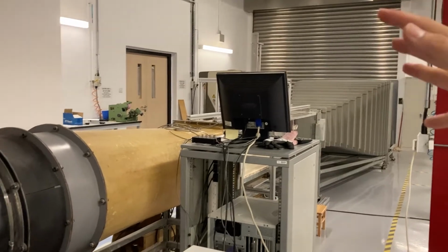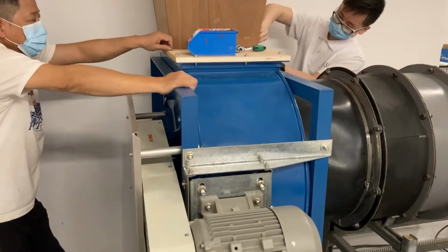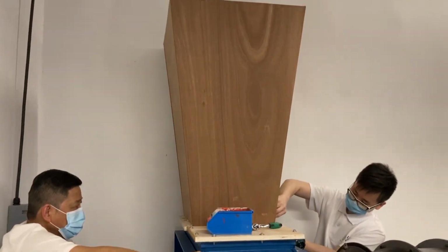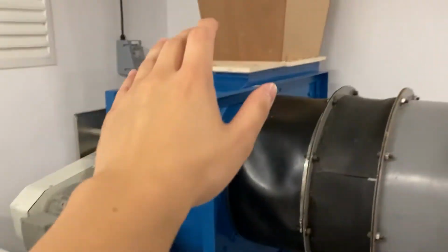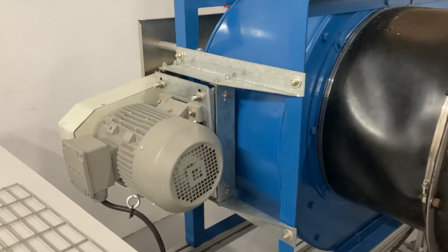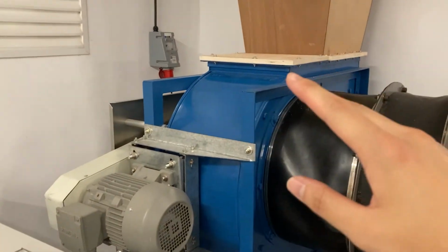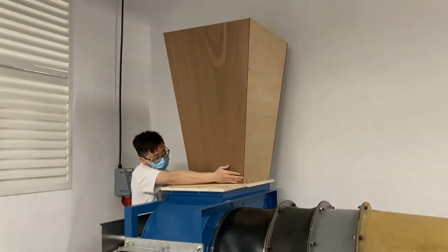So basically, you have the air being sucked in from up there, from this fan here, and out this diffuser that is being newly installed. So before adding the diffuser, it was actually just this metal grid thing that just kind of sat on top of the outlet hole there. And because the flow wasn't being adequately slowed down at the exit, there was a lot of energy losses. And so just by adding this little diffuser, the maximum speed that can be reached by the tunnel increased by almost 40%.